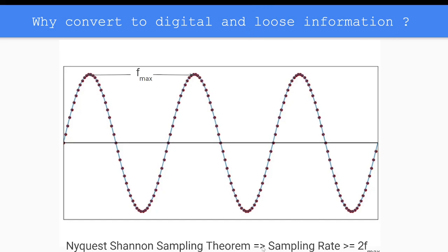It means most of the signal is reliably captured, and we can reproduce it in the same or almost the same shape as we captured it from the environment. So the Nyquist-Shannon sampling theorem states that if you capture any analog real world signal at a frequency which is twice the maximum frequency in the signal, then you are not losing information.